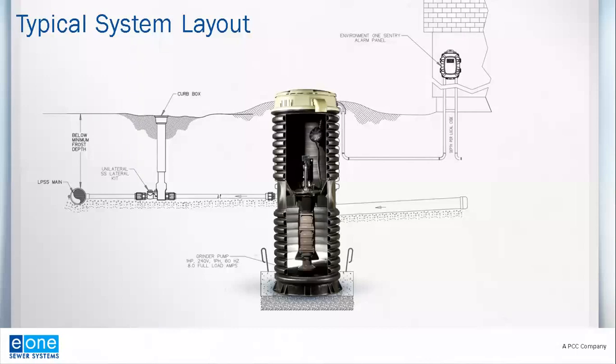There's a distinct difference. We house our controls in our pump for two primary reasons. Number one, it's going to deliver more reliability that way because the pump is climate controlled. Heat and varying, fluctuating temperatures are the enemy of electrical components. So if you have controls up in a panel in a very hot climate, or even on a hot summer day in a place like the Northeast of the United States, temperatures inside that panel could get very hot. So we don't want our controls up there. We want them in the pump chamber where it's climate controlled, if you will.